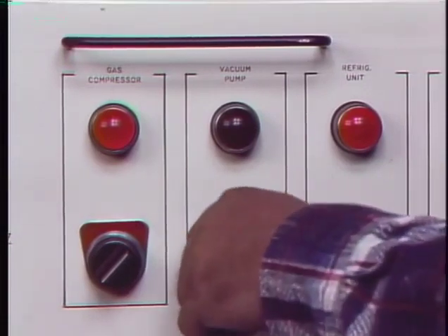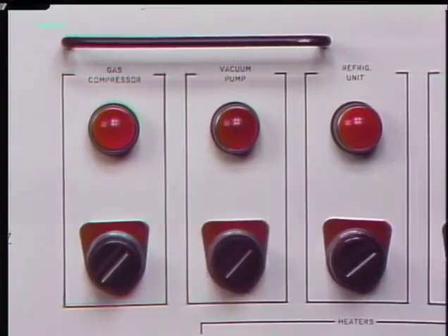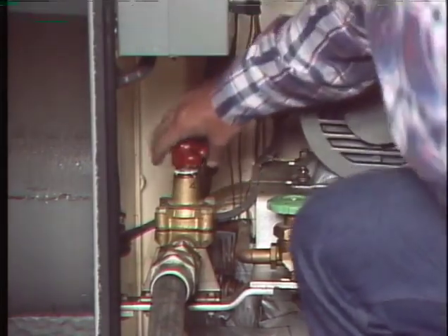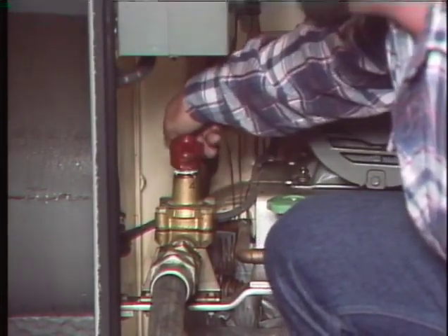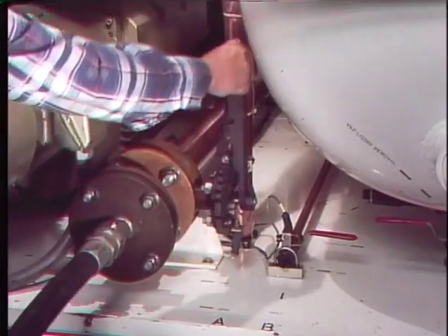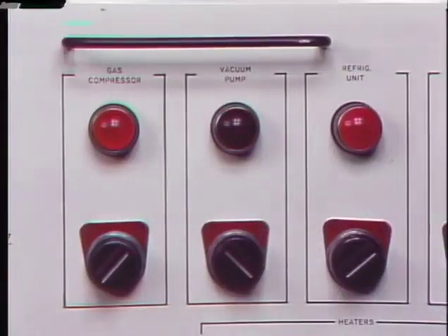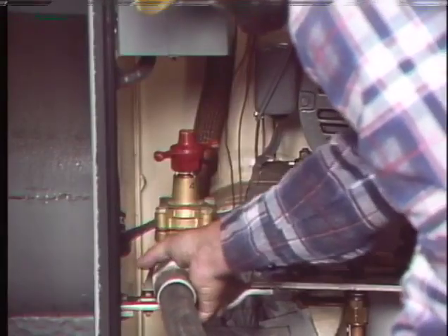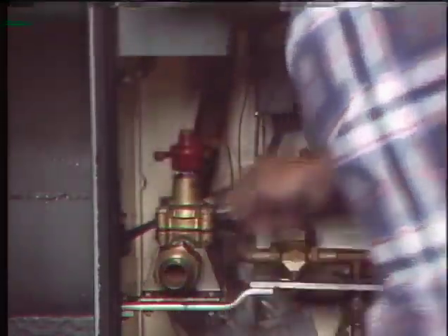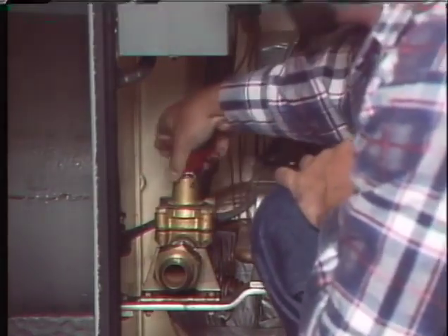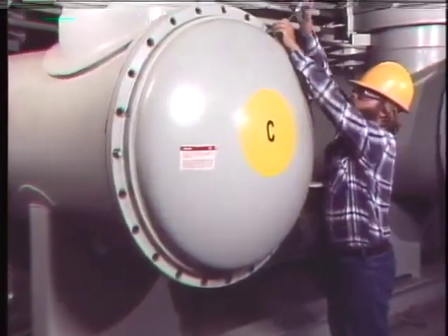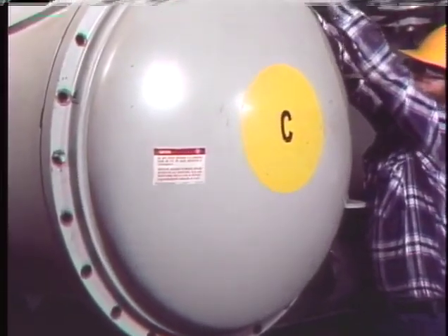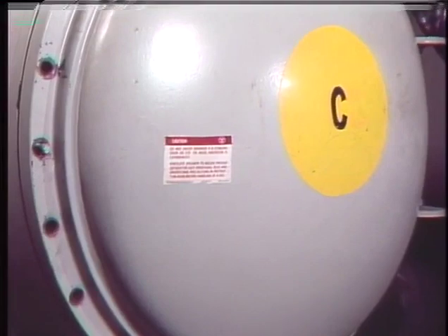Then the vacuum pump is restarted to draw a vacuum in the breaker, ensuring that all the gas is removed. After the proper vacuum is drawn, the main tank cutoff valve is closed. Then the inlet valve at the trailer is closed, and the vacuum pump, compressor, and refrigeration unit are turned off. The hose is removed from the gas service connection, and the main tank cutoff valve is opened to allow air into the breaker. Then the inspection doors are unbolted and opened at each end of the breaker. A little caution should be taken when opening the doors.